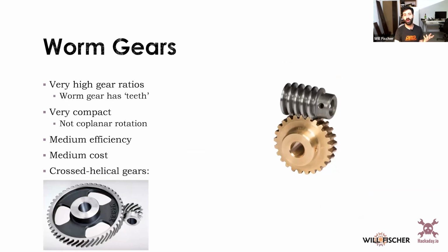Worm gears are able to get really, really high gear ratios because a worm gear is effectively like this one, which is a one-start worm gear, winds the same tooth around the shaft a bunch of times. That makes it a one-tooth gear. And what that means is that here where I've got, I don't know, what is that, 18 teeth, I would guess, on the outside there, I now have a ratio of 18 to 1, which if I need to do that with spur gears, the smallest spur gear you can realistically have is about 8 teeth. Really 10 is better.